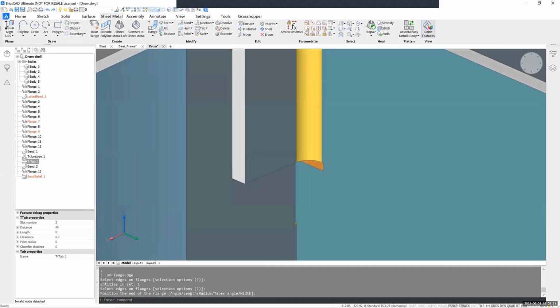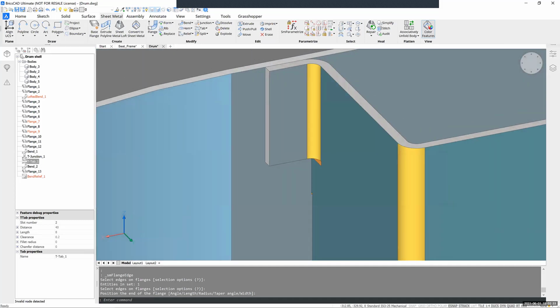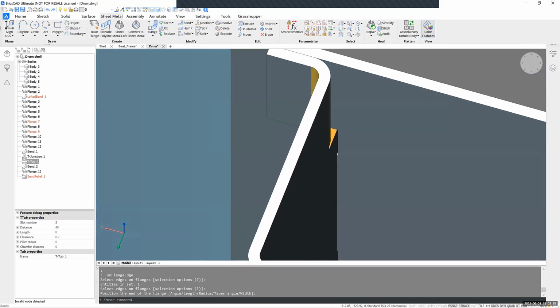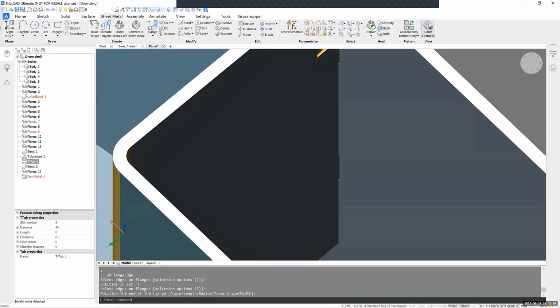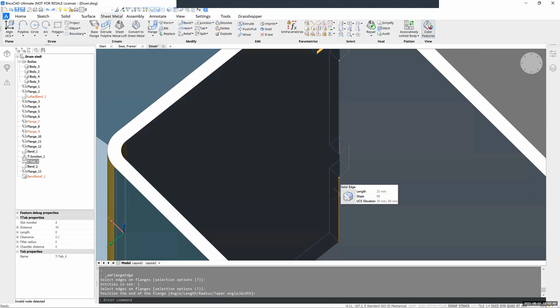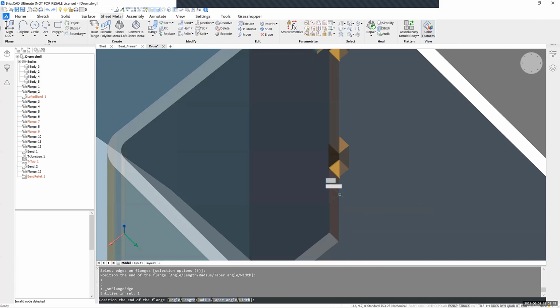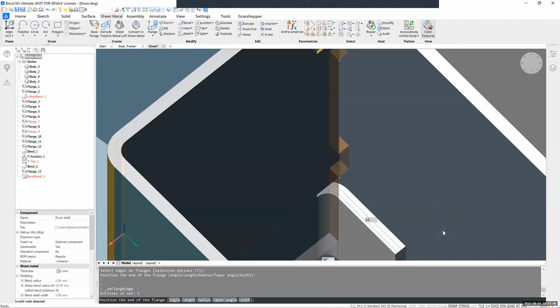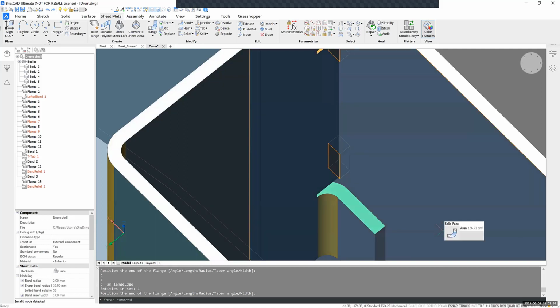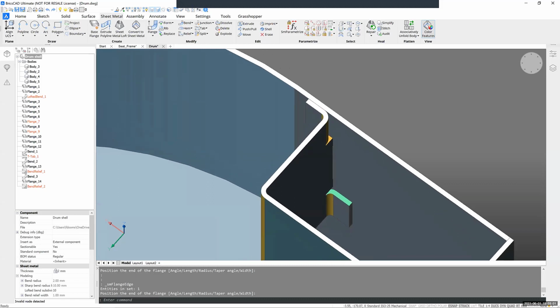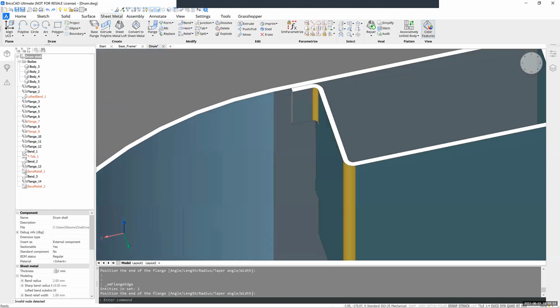So that's convenient because that means it becomes manufacturable. You also want to do the same at the other side so that it's a bit fixed in place, and then you can create the flange from the quad, for example, in this case. And then I can type in 12 and 90 again and accept it. Yeah, you can cycle between the dynamic dimensions with tab. And then you can see this is how I want it.